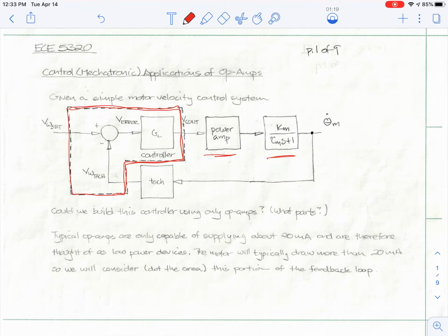And so typically, if there's a motor, the op amps can produce about 20 milliamps on a good day, and after that they current limit, and they do this by folding back. It's a very interesting waveform. If I had a sine wave that was current limiting, it actually folds the current back and will put cups on top of the sine wave like that.